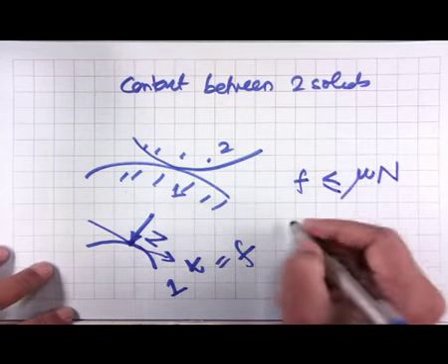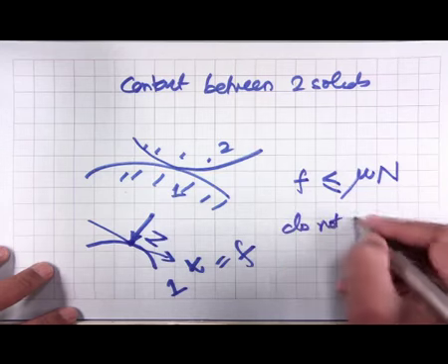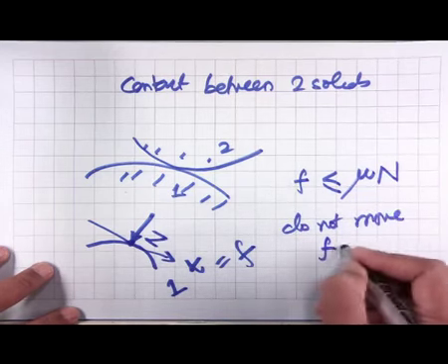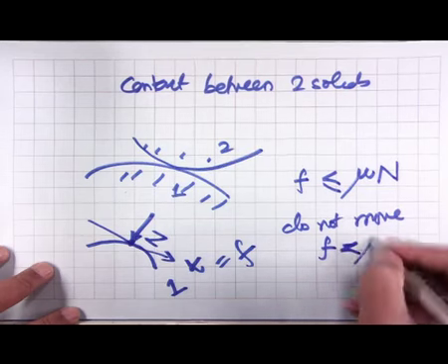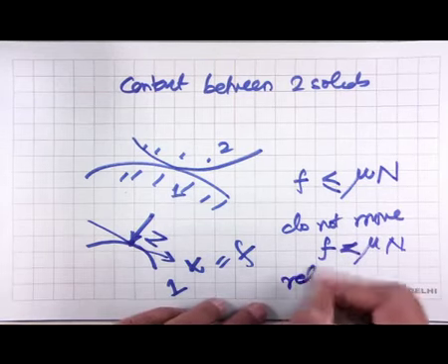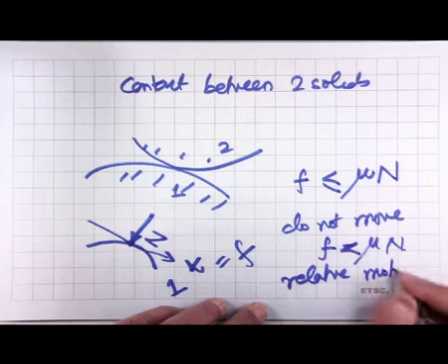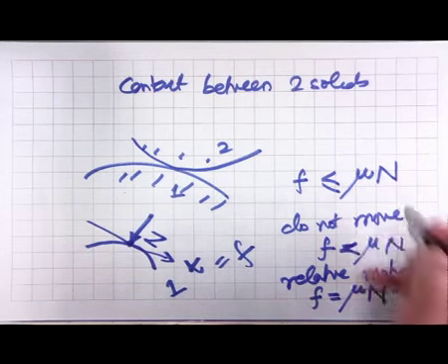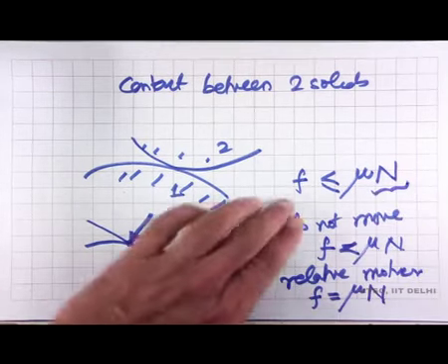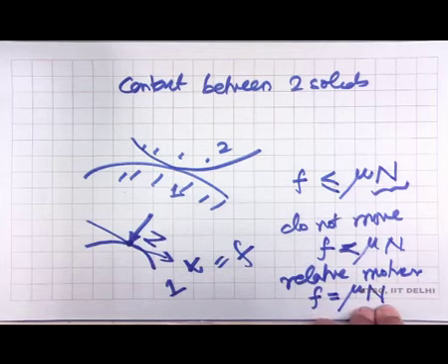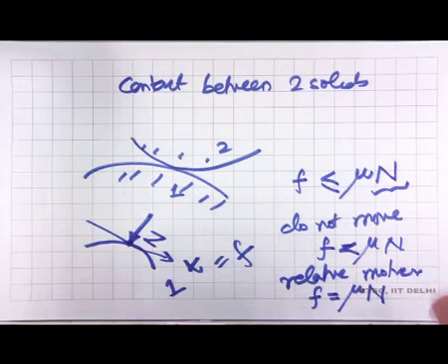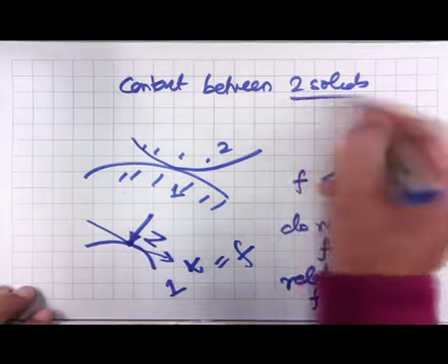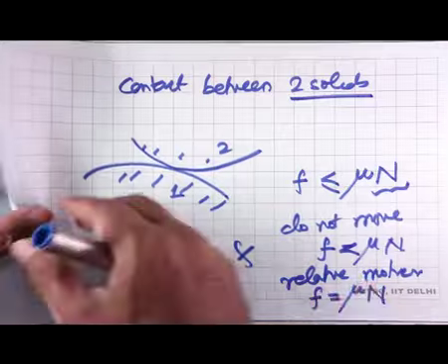When the bodies do not move, there is no relative motion, then this friction force is less than mu times N, but when there is relative motion, the friction force is equal to mu times N. So, that means the friction force is written as directly related to some other force, and that is what happens when the contact is between two solids.